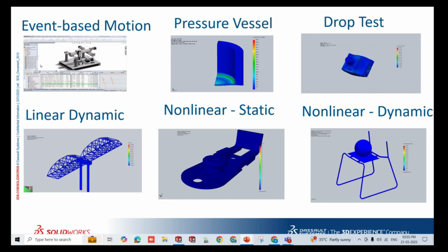Modal time history calculates the response of a structure over a period of time to a time-dependent load. Harmonic analysis determines the steady-state response of the structure to harmonic loads or excitation. Random vibration predicts the response of a structure to random vibrations. Response spectrum analysis is used to analyze the peak response of structures to transients, as in earthquakes.